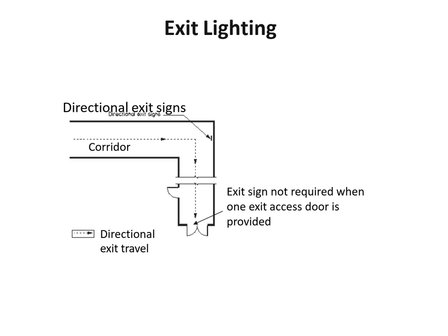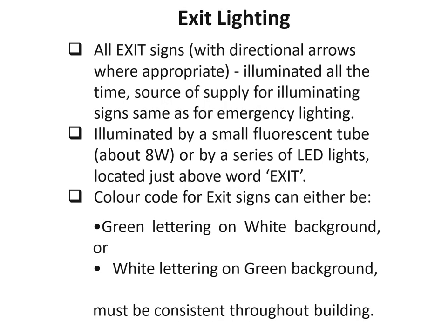An exit sign is not required when one exit access door is provided. So there are these kinds of exemptions worked into it, but it's always good to have. The code always stipulates the bare minimum. As designers, we can design above and beyond, if you think it's beneficial during an emergency.